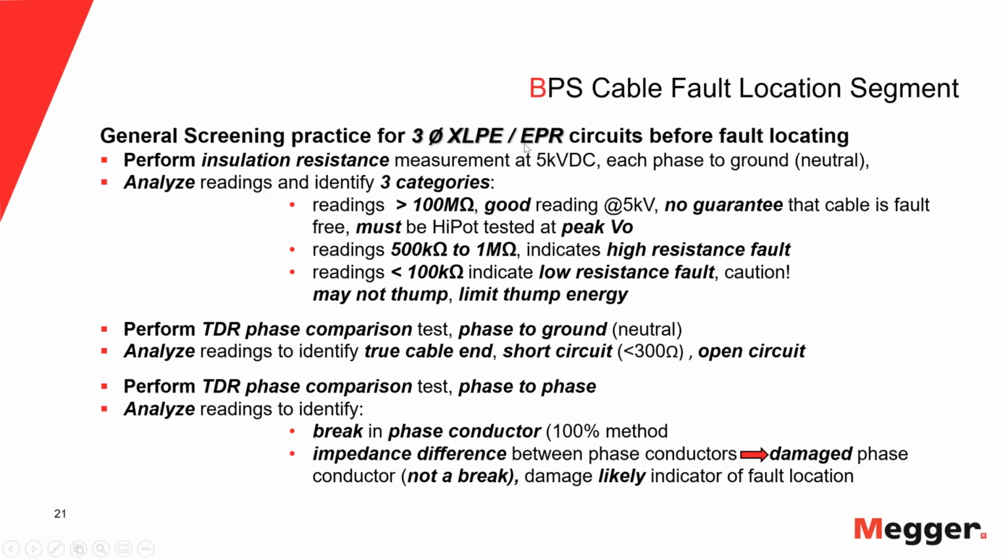That is important, okay? So why do we do this? Because with a TDR, we can do a phase comparison. So we connect phase to ground like we would normally do, and we can compare the three phases to each other. And what we're really trying to identify with that test is whether we're really looking at the true cable end.